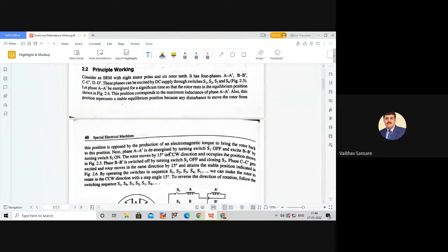When we provide the first pulse, the motor runs with the desired step angle. We sense the position of the rotor, and after the rotor comes to a stable condition, or after the rotor moves with the desired step angle in the forward or backward direction, only then is the second excitation pulse initiated by the controller and provided to the next stator phase.